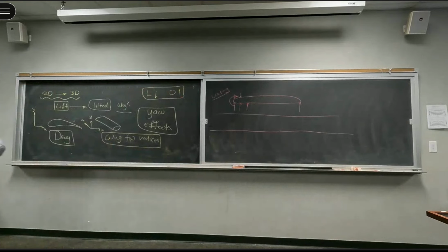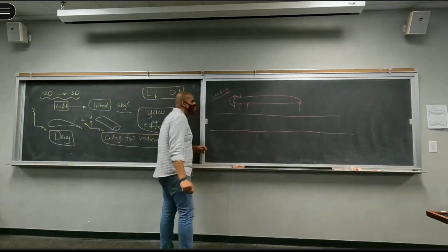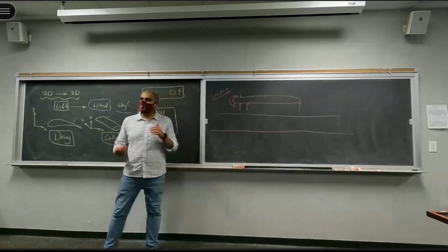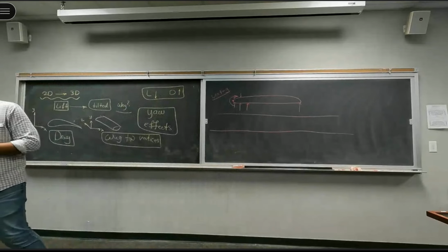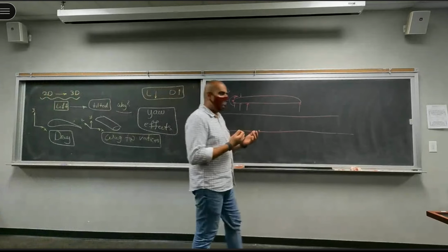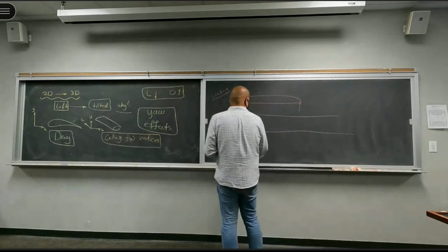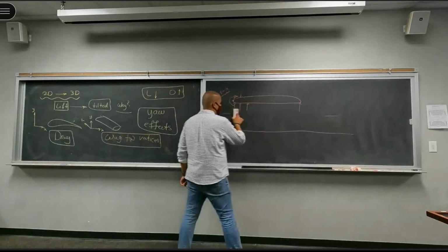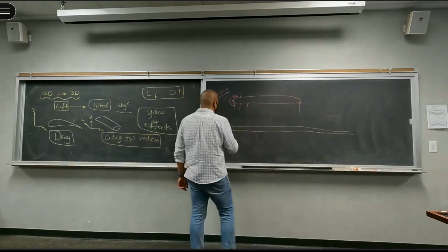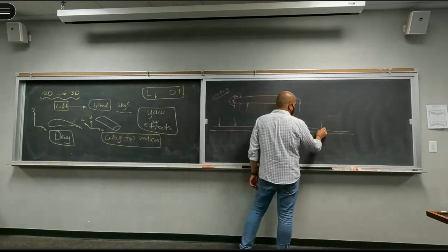Okay. What does this mean? This means that you will lose some of the pressure difference. So pressure, specifically at the tip, is going to become the same on the top and the bottom, and the pressure difference in general is going to reduce a little bit, right? So for a two-dimensional case like this, the distribution of lift on the wing, very thick wing, that's right, is going to be linear, right? Because the pressure difference is going to stay the same all over. And this is an infinite wing, right?